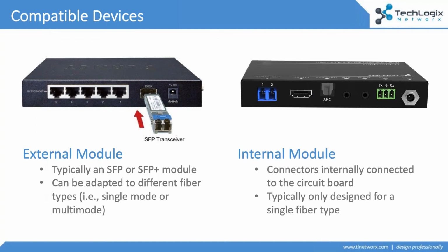Internal modules are fiber optic connections that are physically soldered on the board. Okay, these are physically mounted on the electronics board inside the product. Now, some electronics have these internal modules. We make them at TechLogix, right? And the product is still flexible enough to adapt from single mode to multimode, but we are an anomaly. That is not the norm. Usually a device with a hardwired fiber optic connector cannot be adapted from one infrastructure to the other. So you have to understand what's plugging into your fiber, understand what kind of fiber it can work with, and make sure you're pulling the right cable.